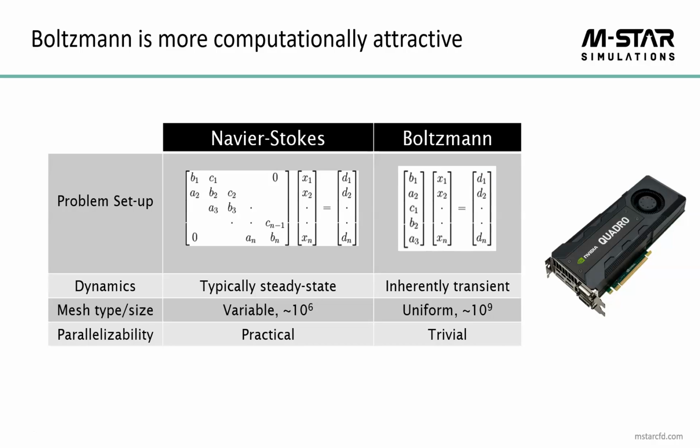When traditionally solving these equations to predict how these fluids move and how the vessels react and whatnot, we typically start with the Navier-Stokes equations, break the system up, and for those who may be mathematically inclined, into a sparse diagonal banded matrix. We relax this matrix to minimize residuals to predict some sort of mean flow field. We typically get the steady state flow behavior. We try to be judicious about how high resolution we go because the problem scales unfavorably with system size, owing to the fact that it's this banded matrix.